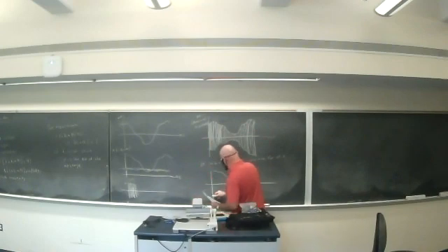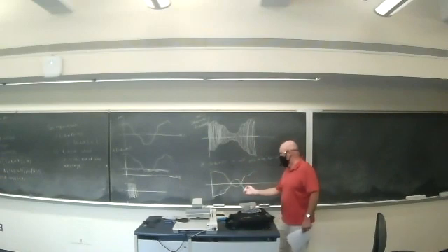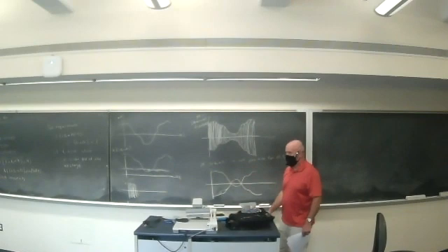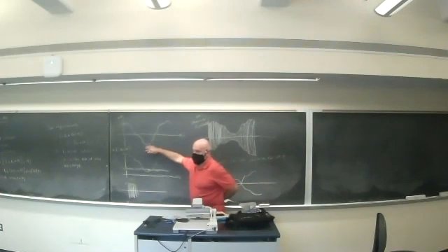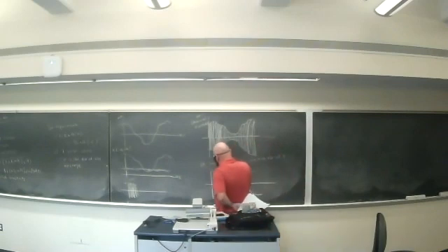Okay, and then the mirror image of that would be, I did a bad job here. Okay, that would be the mirror image. Okay, this would be the case where 1 plus Ka m(t) goes negative. And it's negative during this portion of the waveform. The offset 1 wasn't enough to offset the most negative value here. 1 plus that scaled version of that is still negative. Okay, so again, the AM waveform would look like this.